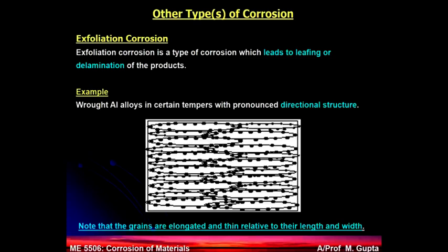So that is the importance of the microbiological corrosion. So macrobiological corrosion, the biological organism you can see with your eyes. Microbiological corrosion, something which you cannot see with your eyes. Macrobiological normally happens on the outside surfaces, but microbiological are more dangerous, and they happen inside, like inside the tank, inside the pipe, and all this thing, something which you cannot easily see. Even if it's happening outside, you cannot really see it. So that is why we have to be more careful.